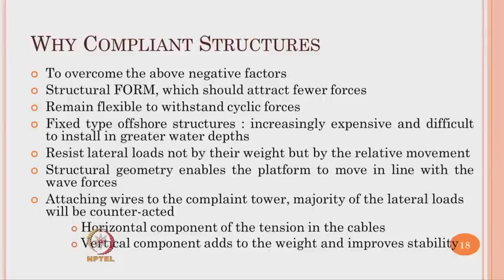The structural form is generally advisable and recommended. It should attract fewer forces in comparison to the fixed type structures. The structure should remain flexible to withstand the cyclic forces, which was not possible in the case of fixed type offshore structures. Fixed type offshore structures became increasingly expensive and difficult to install in greater water depths, therefore, compliant structures were thought of. Compliant structures resist lateral loads essentially not by their weight, but by their relative movement, that is why they are called compliant.